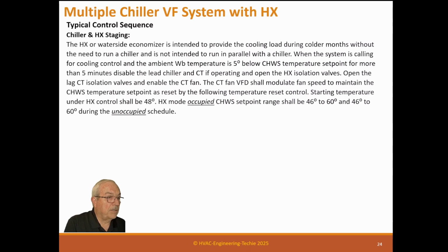Now, the reason these set points are different than what we talked about in other ones is because this is never going to work at maximum load. The heat exchanger will never be online during maximum load. It's always shoulder load. And so we're trying to use this. And if you have a system that runs 24 hours, it'll always come on at night. So you need to be prepared for that. These work very, very well in higher temperature areas or high altitude.